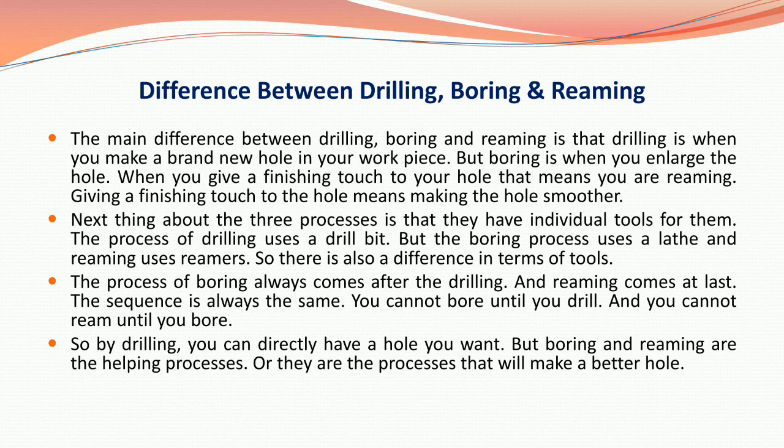The process of boring always comes after the drilling, and reaming comes at last. So the sequence is always the same. You cannot bore until you drill, and you cannot ream until you bore. So at first you need to drill, then you need to bore, and last of all you need to ream.